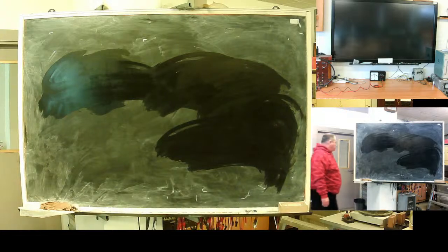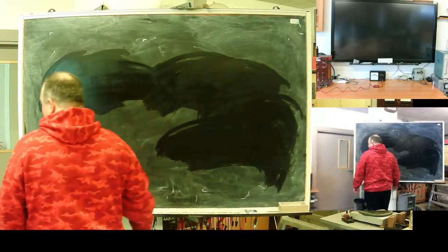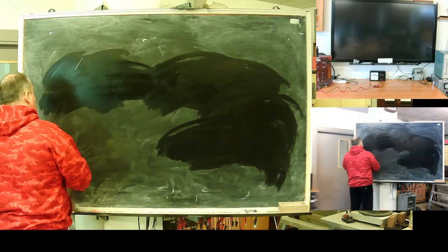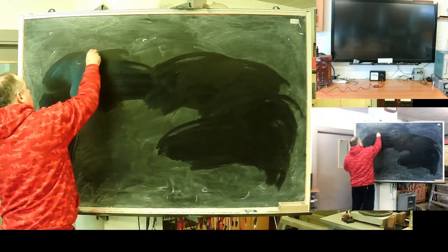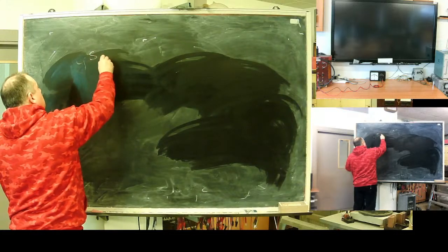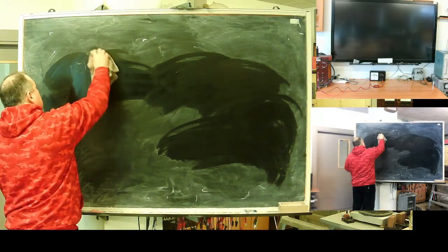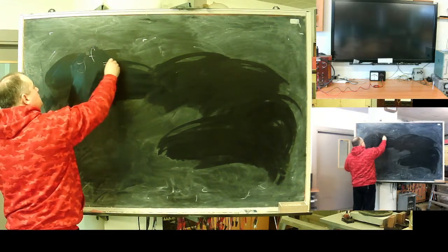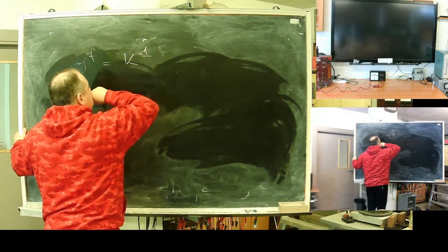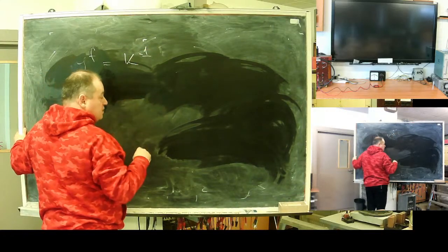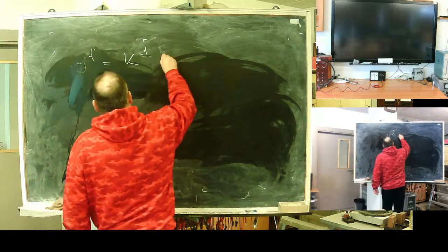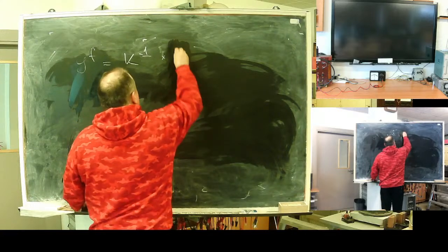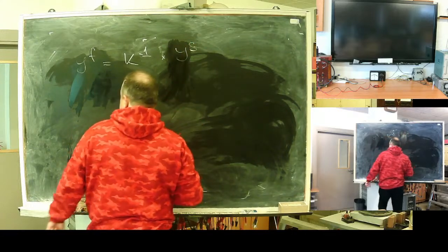Let's go forward, and what's forward? What's the inversion transform? Let's say Y in sequence. Why Y in sequence? I need it in phase coordinates. So in phase coordinates it should be the inversion of the Fortescue matrix multiplied by Y in sequence.